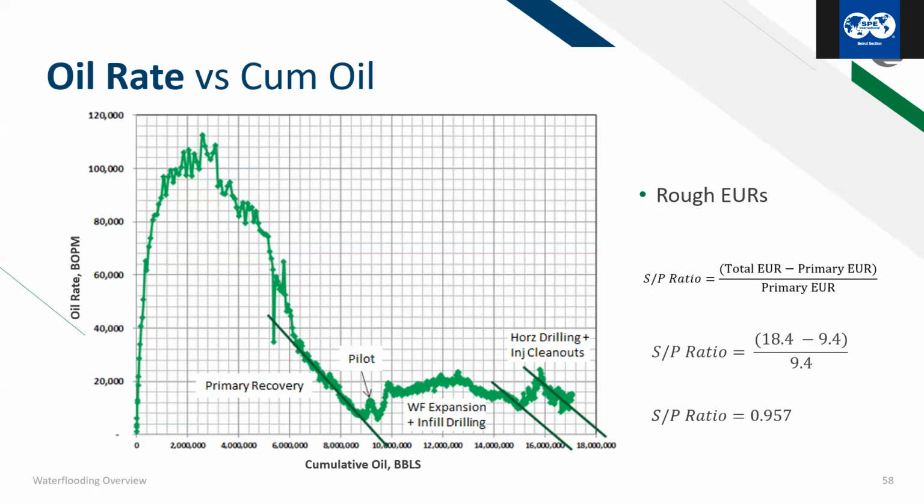And the reason I'm bringing that up here is because when you're doing decline curve analysis and even drawing the tangent lines here, this tangent line or even a decline curve at this point would be dependent upon your injection rate. So as soon as your injection rate changed, this line or your decline curve would no longer be valid.